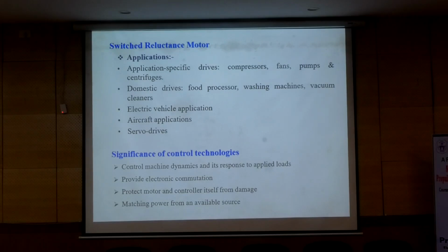And to protect the motor and controller itself from damage, we can talk about the protection and safety of the machine, which can be resolved by means of fault tolerant techniques, by devising appropriate fault tolerant converter and inverter topologies, so that we can make the drive safer.